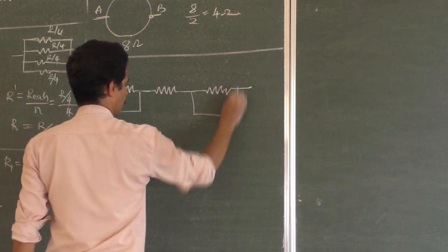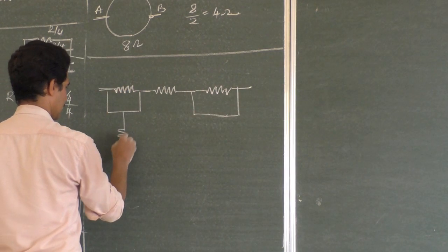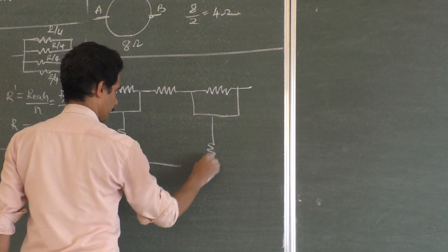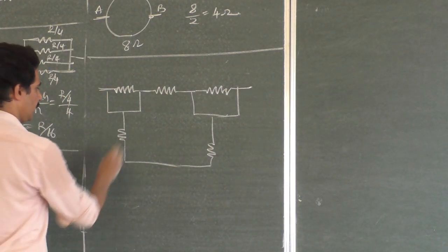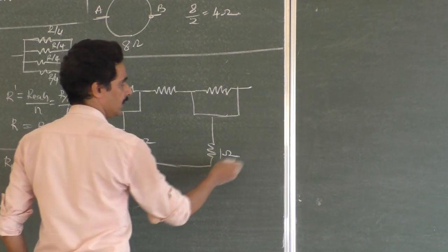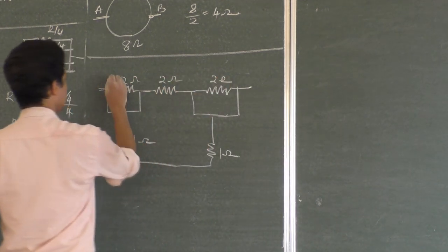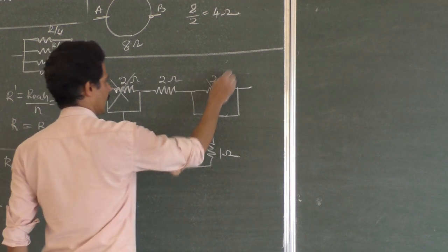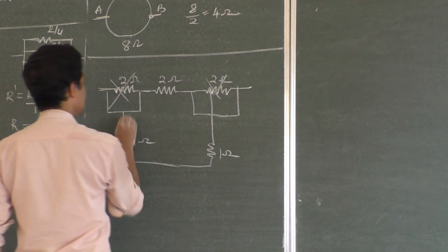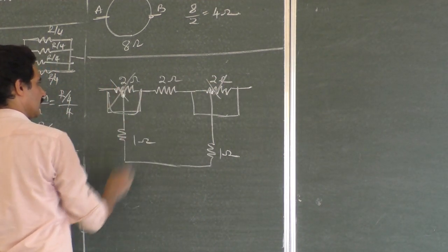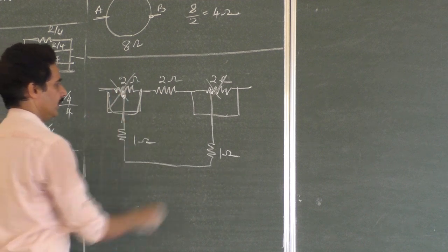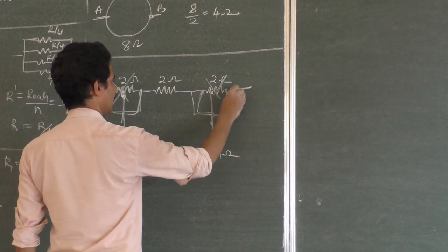So coming back to the board now. The resistances are like this, right? This is 1 ohm and this is 1 ohm, and these are all 2 ohms. The problem is this is shorted, 0 ohm. This is shorted, and this can be connected directly here because everything is a short. It is as if you are connecting it here and here.